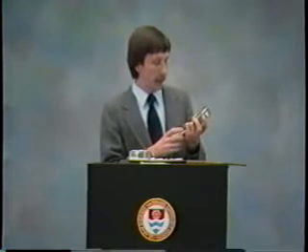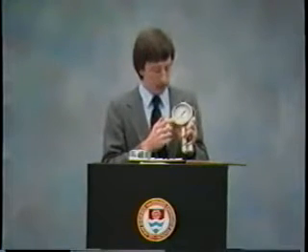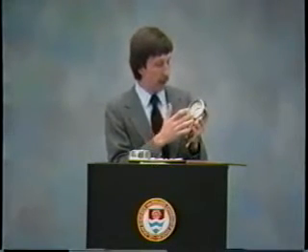The other thing to remember about these gauges is that flow is related to the square root of the velocity head. Therefore, for very small pressures, this gauge is very inaccurate, and it becomes very accurate up at the higher range. So you'd like the readings to be on the higher range of the gauge, which means that if the gauge is reading at the lower end, you probably need to replace this gauge with another gauge.